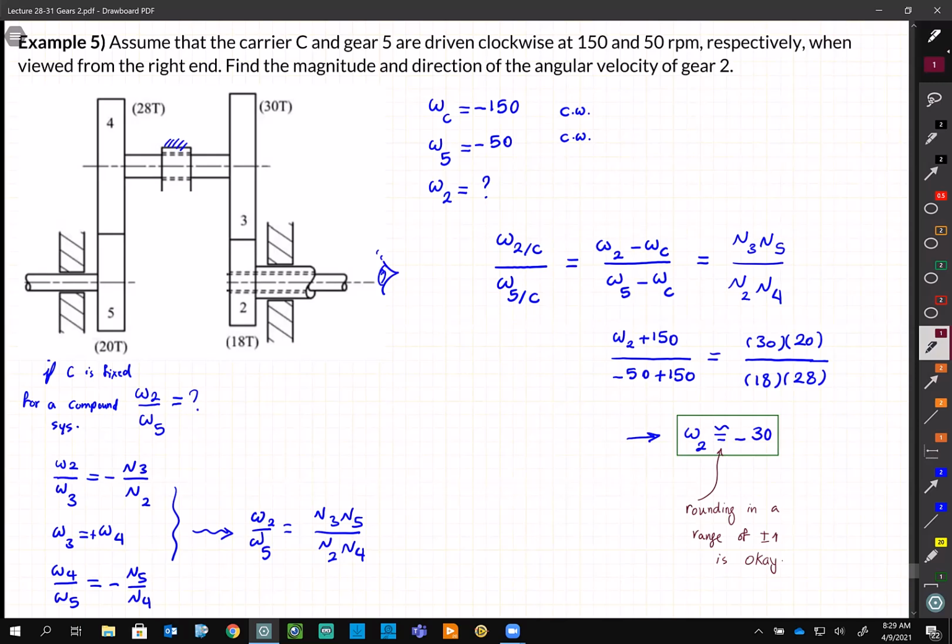However, in future, in your work, if you write down 30.95, it means your system is so accurate that the accuracy of rotation is going to be in a range of 0.5, or 0.05. Unless it is one of those gears in Swiss watches, right? Super expensive gears, then you can claim that. With regular gears, plus minus one is actually correct.